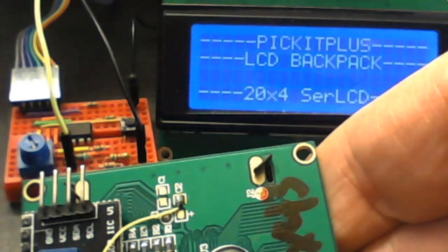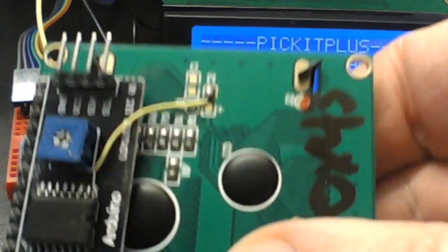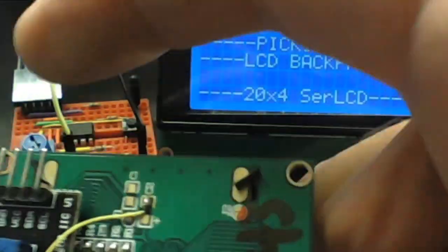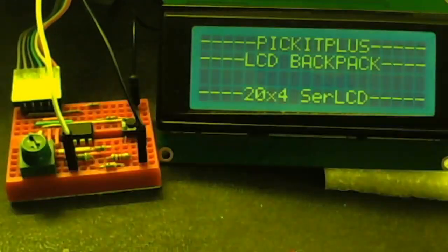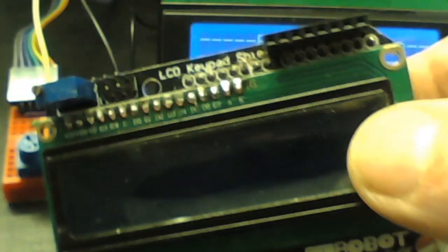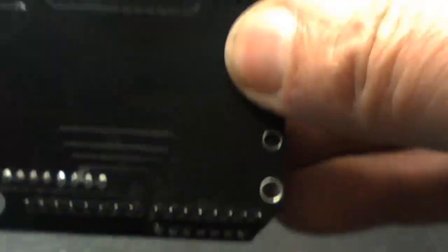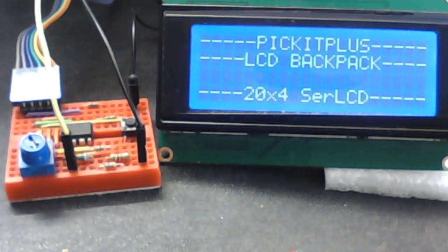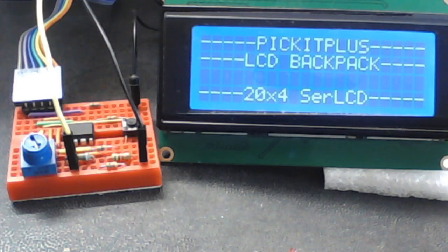This one uses a serial connection. You can see it's Chinese, therefore it's bodged up. This is a serial connection but requires 2 wires, and that's called I2C, or TWI if you're an Arduino user. I just don't want to be setting that up today. The same software will control one of these, which is an Arduino board. Look, it's an Arduino shield. So what we've got is a really simple way of connecting an LCD, a bit like one of these, to my chip through one wire.